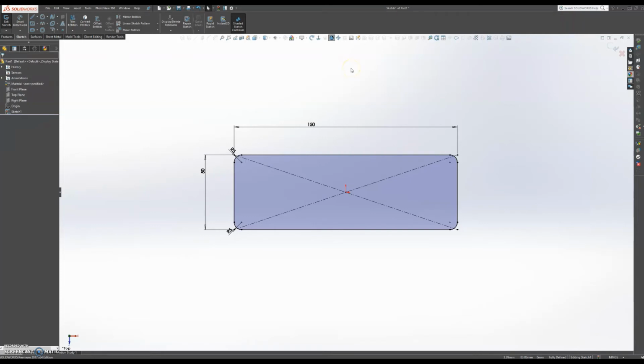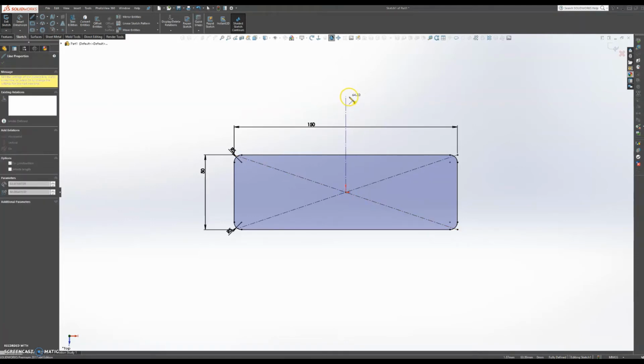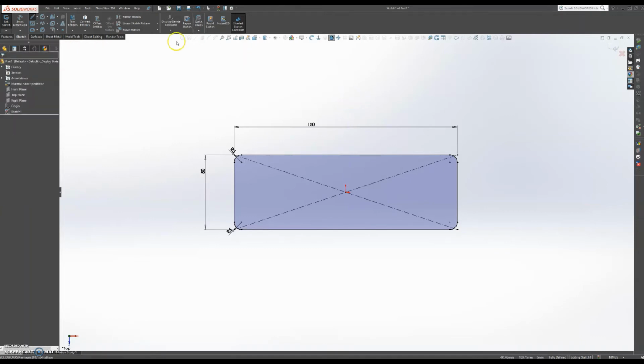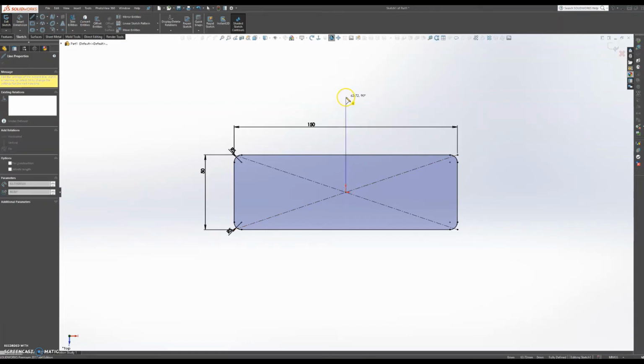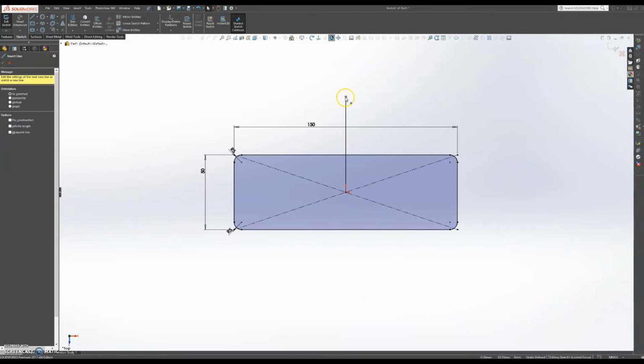Okay, and then what you're going to make first is go to the line here, and then you select center line, and this will be a construction line. If it's not a construction line, if it's a line, then what you can do is put this in the center, right? And there are two ways to get out of it, as you see it keeps moving around. You click it again at the point and it gets out. Double click it back at the point and it gets out.